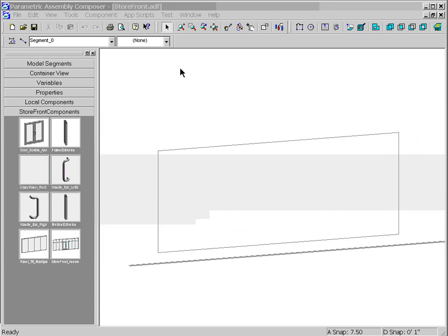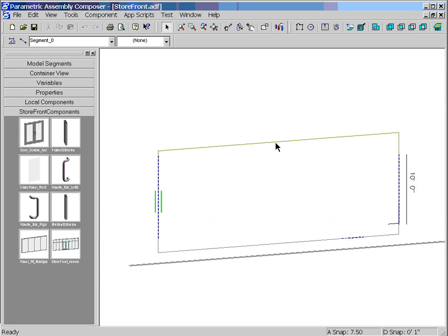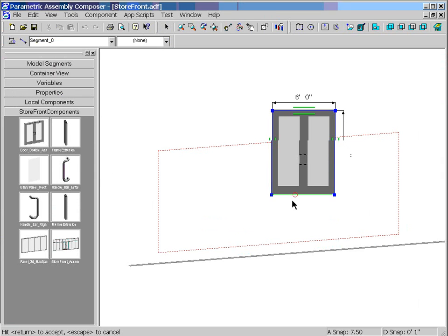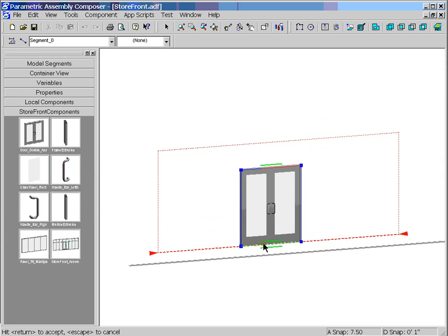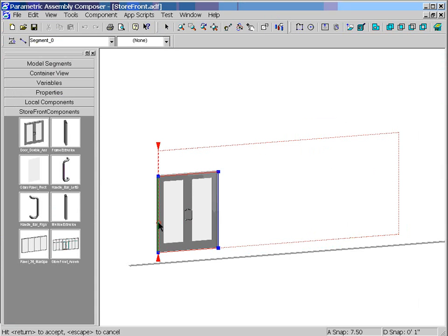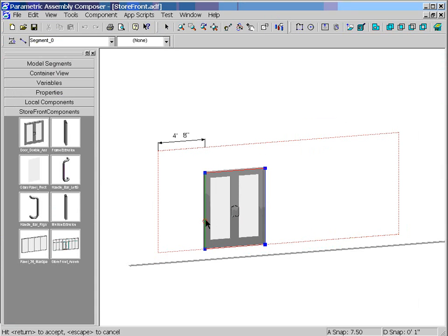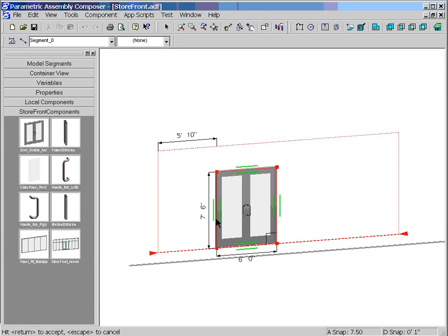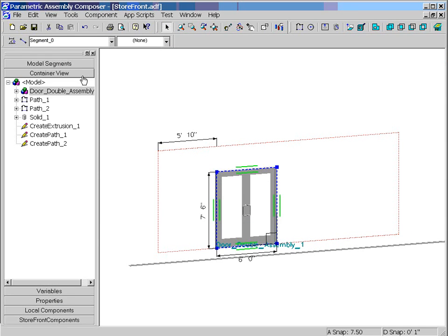Let's take an example of a curtain wall. We could take this facade and apply what we call a path to the facade. From our kit of parts, basically parametric cells on the left-hand side from the component section, I can drag these pieces out onto the facade. I can then click on the door, which exposes some rules.